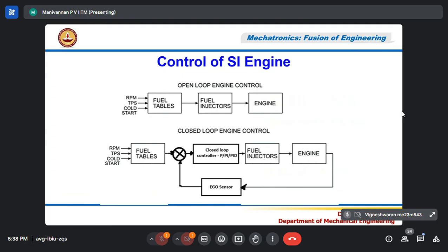Okay. Sir, last question. Sorry. Since we are using an engine speed sensor, we have to change the angle. But if we use, say, a crank position sensor, and we fix a position at which the spark should happen, then we don't have to change this, isn't it? Or is there also a change? No, you have cam position directly. If we have a cam position sensor, then you don't need it, but anyway you are going to change. Based on cam position, you are going to change.